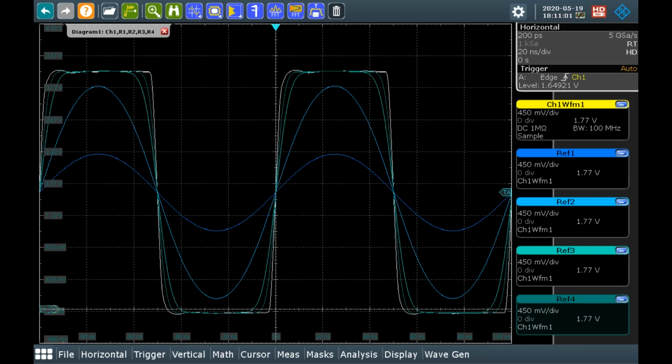Okay, Greg, questions? Yeah, we had a question. It says, do I have to use an active probe to get full bandwidth of my oscilloscope? No. So we do recommend active probes in general. You will get the fastest rising edge by doing that. If there's a lot of questions about probing, I think you're really going to be interested in Jeff's discussion on Thursday. One of the other things that you can do is cable directly in or solder into your device.